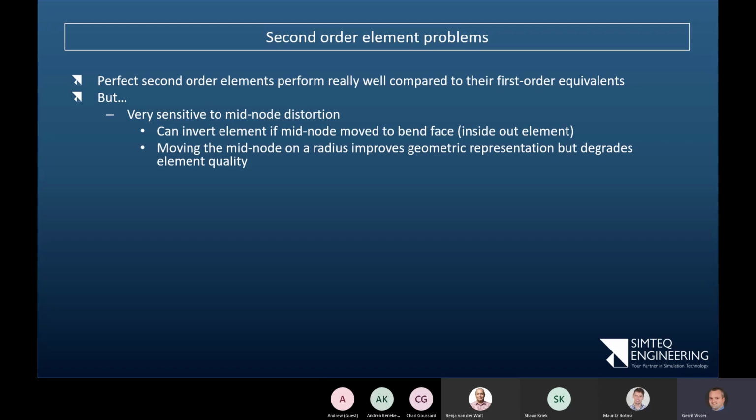And it's really easy to get that kind of element in a model. What that means is that the element cannot be solved, period. The solver will just stop. It's not a really bad element, it's an impossible element. So in that case, we have to try and remesh a bit to get to the point where none of the elements are inside out, at least.